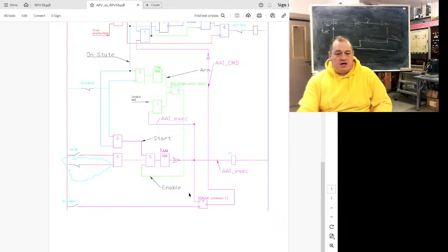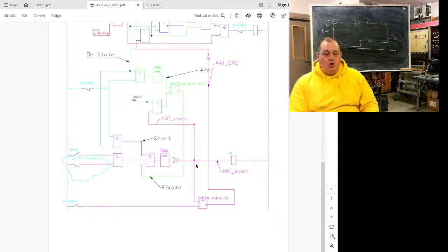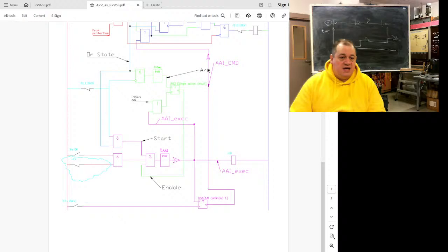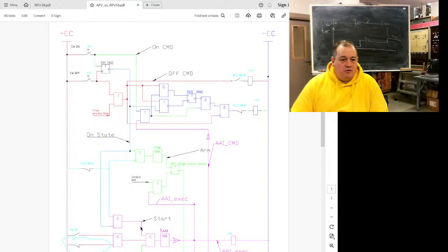So this circuit, when the command to switch on comes, sets this trigger and it will hold auto reclosing, from Latvian, automātiski atpakaļ ieslēgšana. It's the auto reclosing command, and it will hold until the signal that the switch is on arrives. And now what here? What's this circuit?